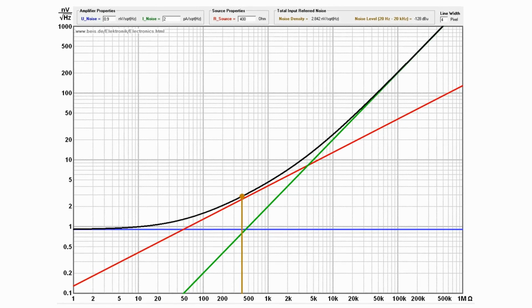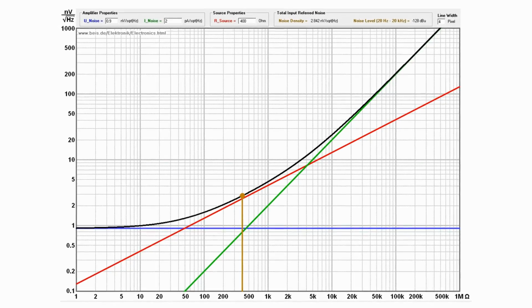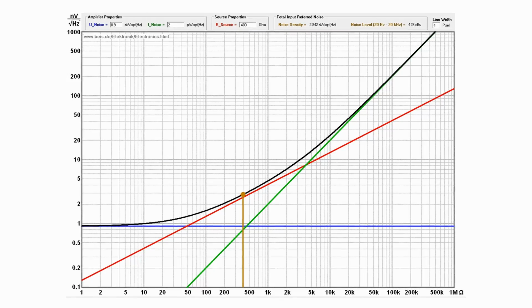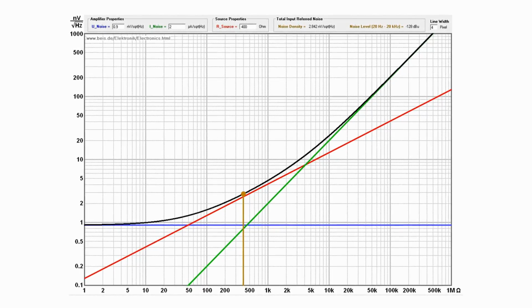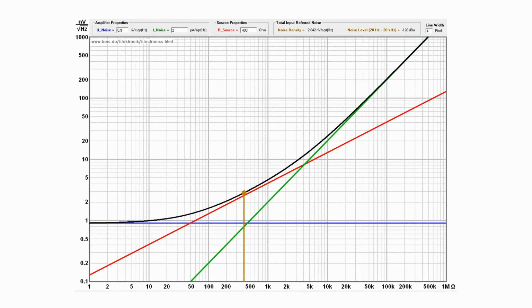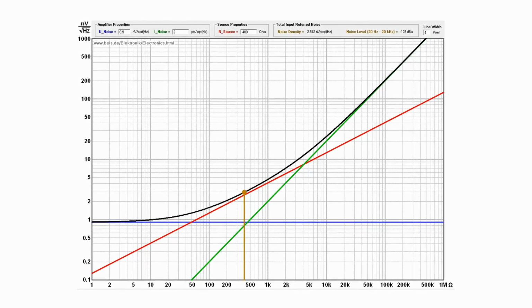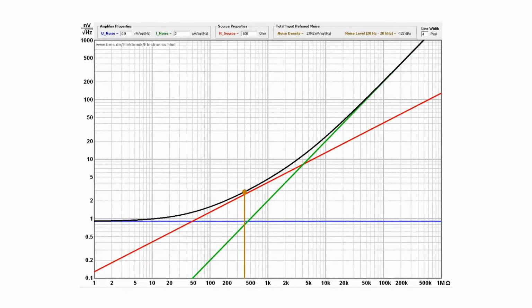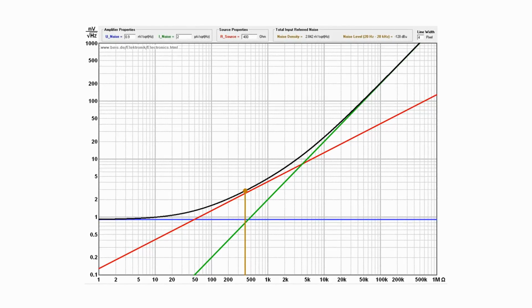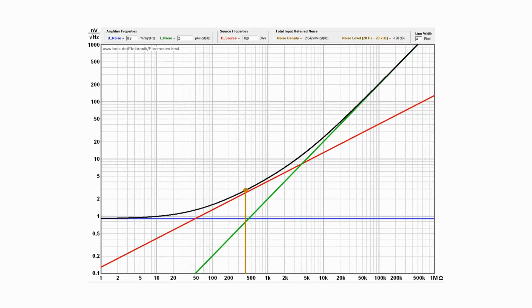And secondly, you now hopefully understand that testing the noise performance of a preamp isn't that simple after all. There are several variables like the impedance of the mic and the technical properties of the preamp itself. And keep in mind, this stuff then usually varies with frequency and temperature, and I didn't even mention the usually negligible so-called flicker noise, so we just scratched the surface here.